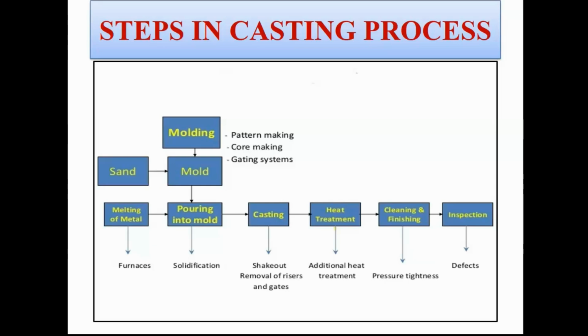In the simulation, it will show you how the material is filling inside the mold cavity, what the temperature distribution is in the whole casting material, and how the solidification is taking place. So you can visualize and have a prediction about the different casting products and the quality of the product after the solidification or casting process is completed. If you have any interest, you can go through that particular software called Flow 3D. I also know some other specialized software.